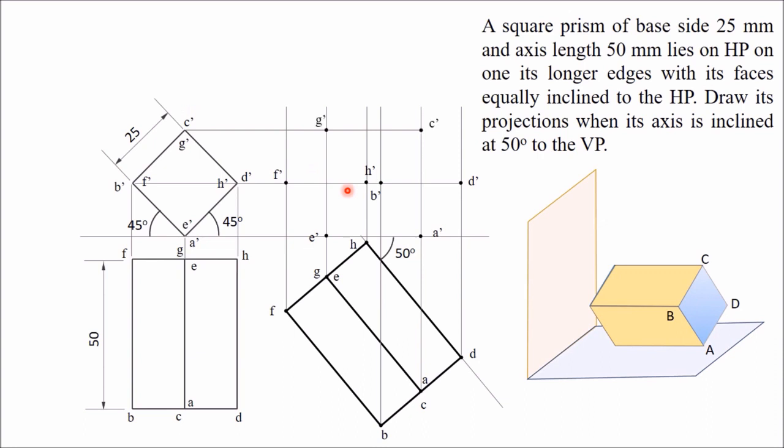G and C. When you look from this side, you will look from the bottom and draw this. So you can see this entire face is visible, that is A, B, C, D is visible. So draw A, B, C, D first with solid lines, and after that draw the outer lines. Completed. And when you look from this side, this BF is visible. I have drawn BF also.